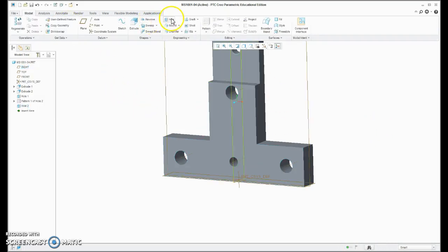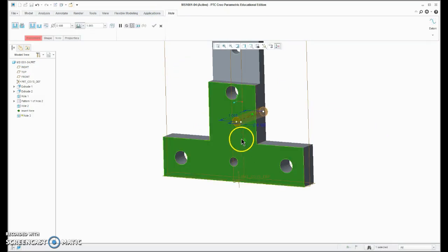And then I have an additional hole. It goes up here, aligns again. And the nice thing is, I'm always going to want these holes to be in the middle, because that's kind of the point of this part, is that it's a symmetric part. Drop that down to 0.95. So even if this gets wider, these holes in the middle that I'm aligning are going to stay here.